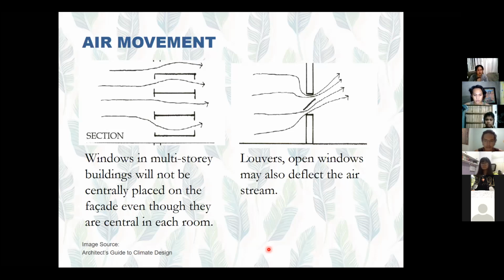And also, louvers will affect the airstream. They deflect it. So, will you have it this way or the other way? At the same time, there is privacy, since louvers offer visual privacy. And if they are inverted, as indicated in the image, the issue, if this is part of the fenestration, is that when it rains, water will enter inside.